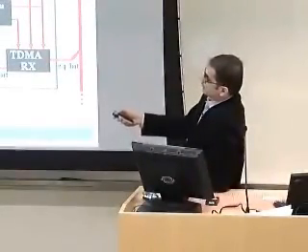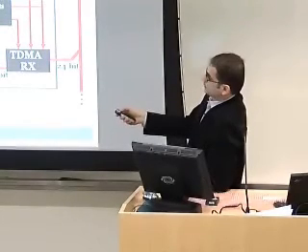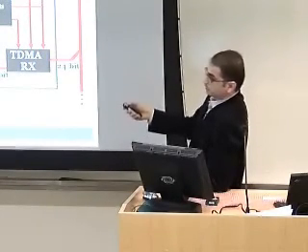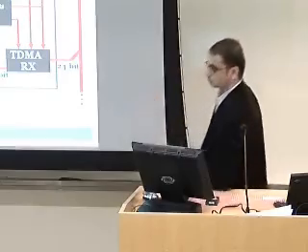Now, as soon as a packet is being received by the CPU, it's stored in the transmission FIFO, and the TDMA transmitter will continuously check to see if there are packets. If there are packets, they will be fetched immediately, and when the slot of the CPLD becomes active, they will appear on the channel. Whenever the slot of the CPLD is not active, data will be automatically received, and it will check if they're destined to the CPLD. If yes, they will go into the reception FIFO, and the memory status signals will be updated.